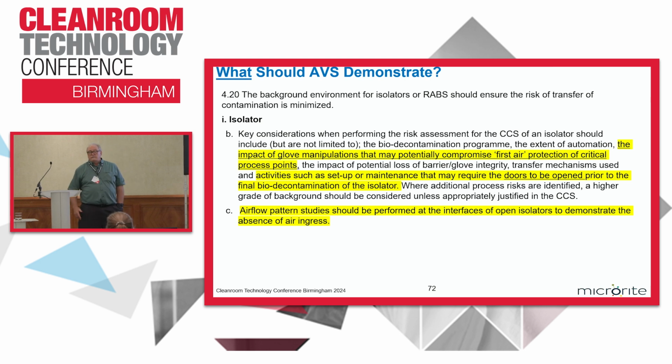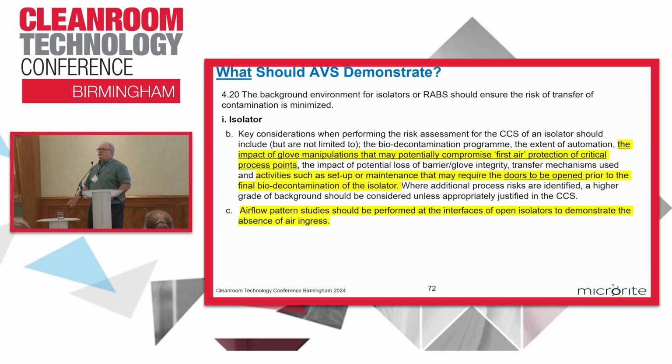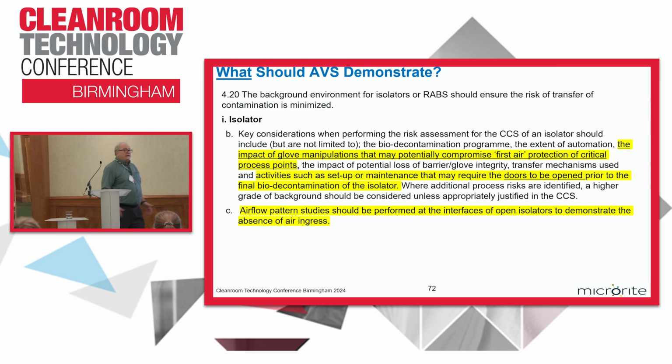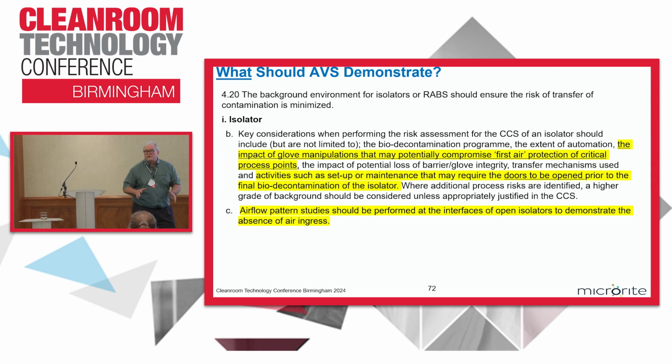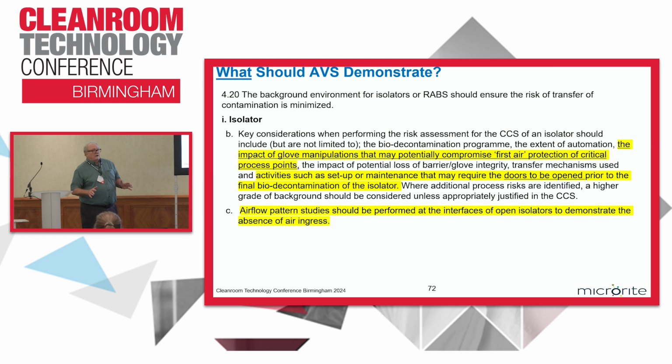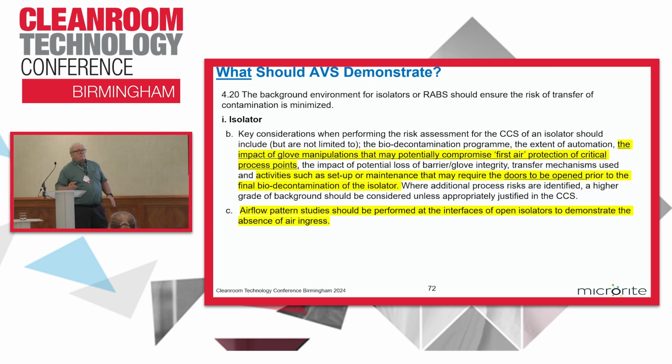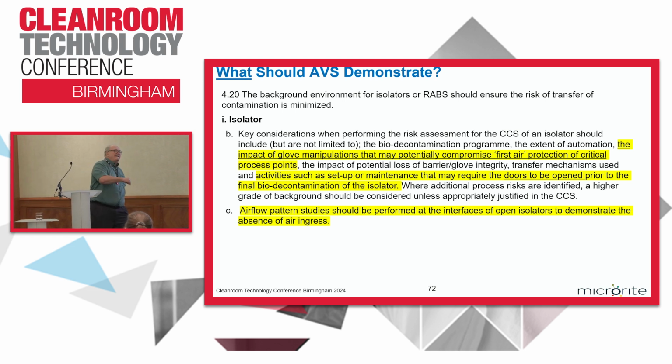That intervention would include them sanitizing their hands, entering the isolator, inspecting their gloves, picking up the forceps, removing the jam, and then setting the forceps down or back where they go and exiting the isolator. That would be the full intervention that you would capture, even though smoke is only a smaller portion of that entire test. It doesn't take that long to do, but the whole point is you're simulating that intervention.